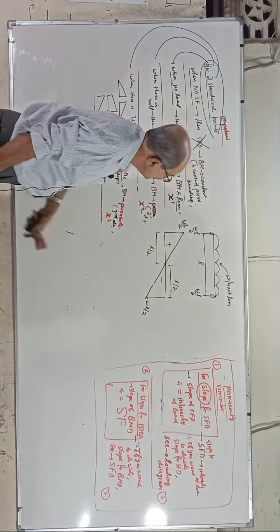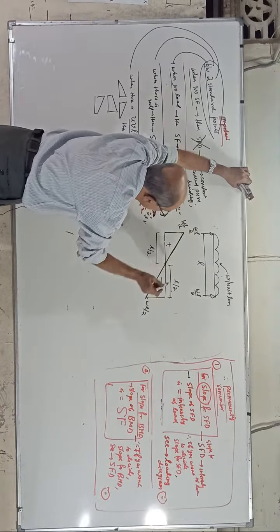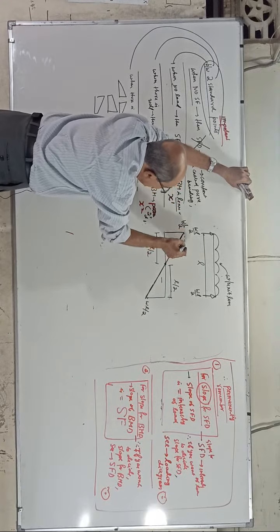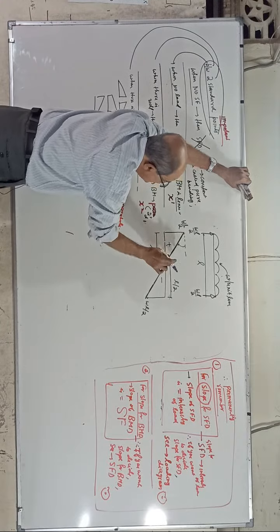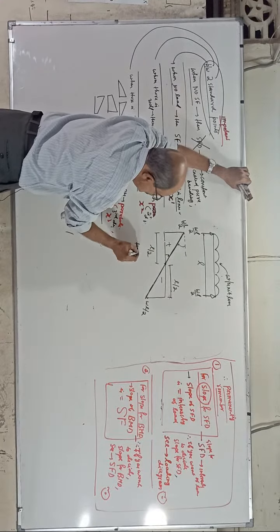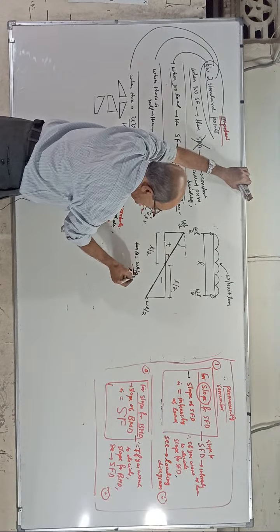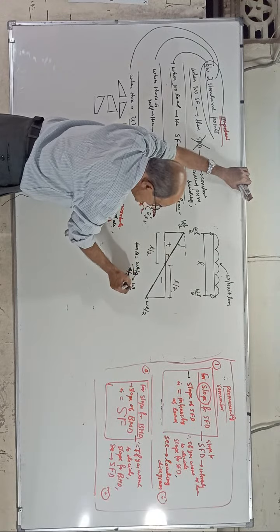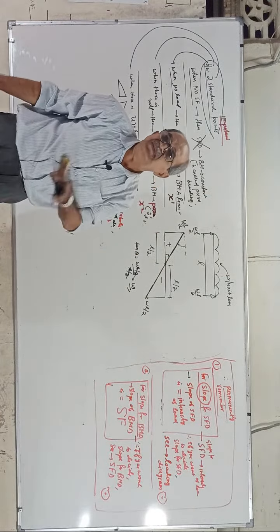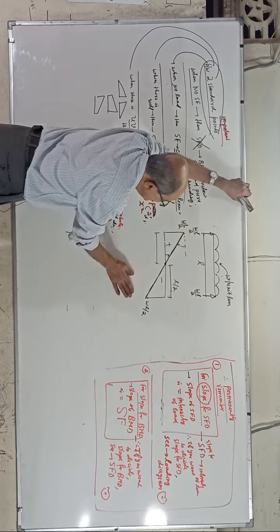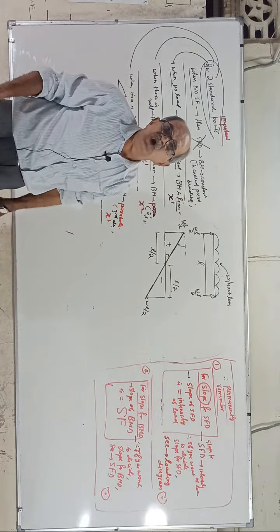Okay, now, see now. Tell me, what is the slope of this plane? Entire line. See here. If you want slope of the entire line here, you can tell that slope equal to this slope. Correct? Tan theta equals WL by 2 divided by L by 2. L by 2 cancels. Once again W only. So, slope of shear force diagram is intensity of load. Since it is linear, nobody got confusion. Nobody will have confusion. This everybody knows. I don't have to waste time.